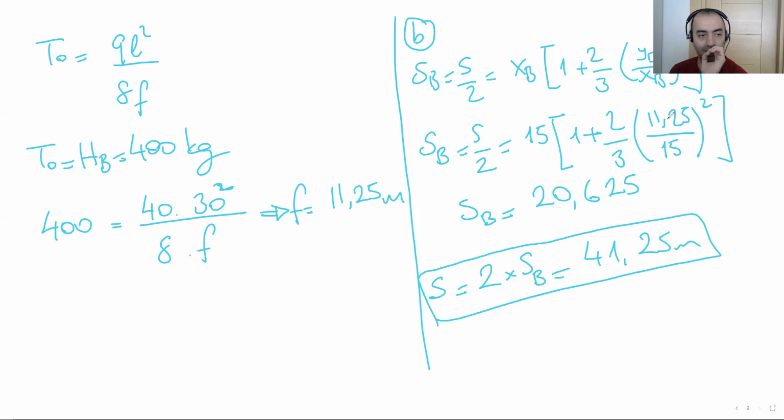T0 is the minimum tension load at the very bottom point of the cable, because there is no vertical component at that point. If we go above toward the support, we see the horizontal component, which is T0, is always constant, and we add extra vertical components.